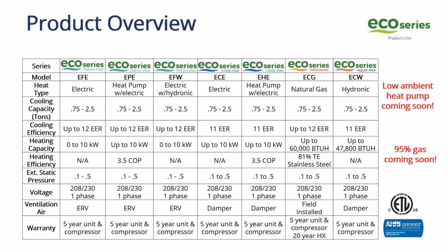We've seen it where maybe it's a warehouse or a facility that was not apartments before that was turned into apartments, and they add our style of units to provide air conditioning, or maybe they only had heating only, and then they want to add the air conditioning component. So it's doable, but there would be a large expense in basically cutting new holes in the side of the building to accommodate it. Yeah, so there's a heavy installation cost, I would guess, is probably the best way to explain it.